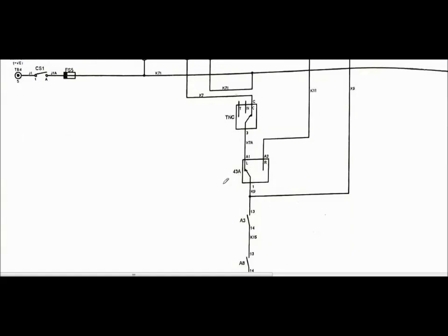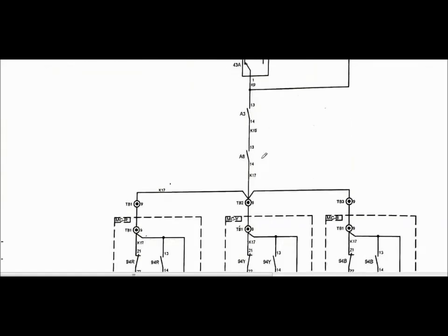local remote selector switch. If we select the selector switch in the local position, then local closing can be done, and if we select it in remote position, then closing can be done from the controller relay panel. A3 and A8 are the contacts for the circuit breaker SF6 lockout contact. Whenever gas pressure is low or lockout, then this contact will be in NO position. If gas pressure is at normal level, then these two contacts will be in NC position.